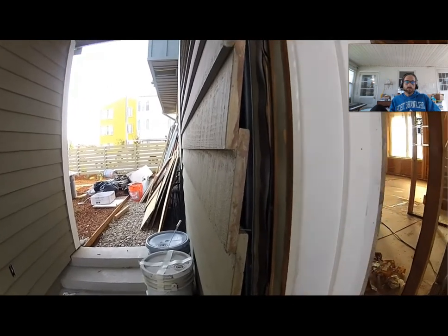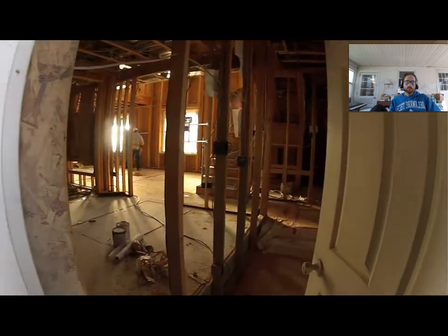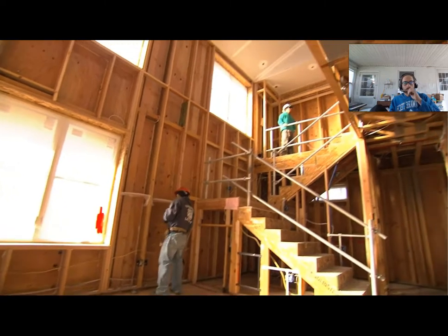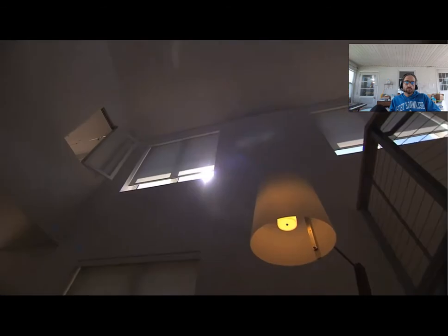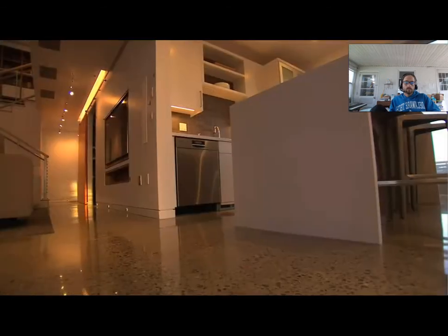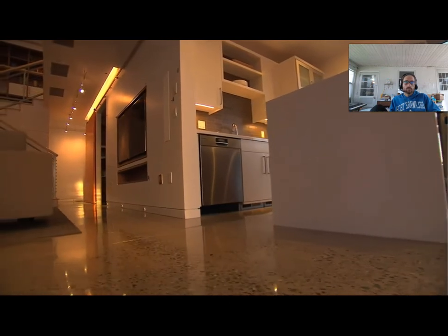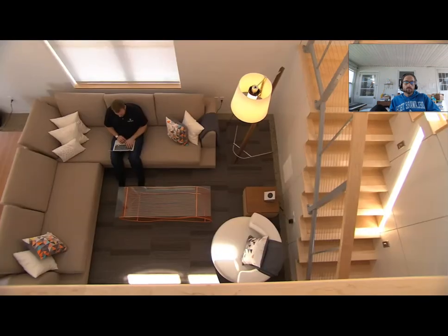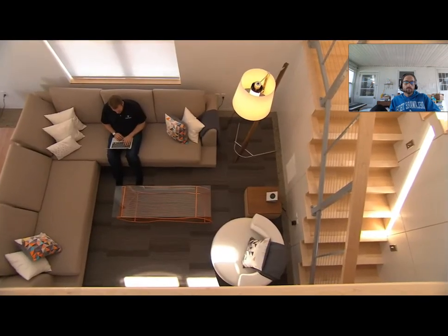The envelope is the outside of the building that basically separates the indoors from outdoors. So that's your walls, your windows, your roof, your floor. The elements of the house include a double stud wall and triple pane windows. The roofing material is a cool roofing material which reduces the amount of heat gain. The slab is fully insulated because we are heating and cooling the house through the floor, and we want all that heating and cooling to actually get into the space and minimize the loss to the ground.